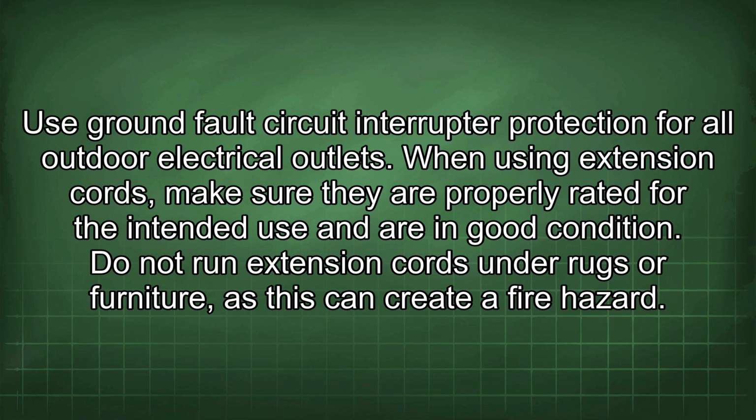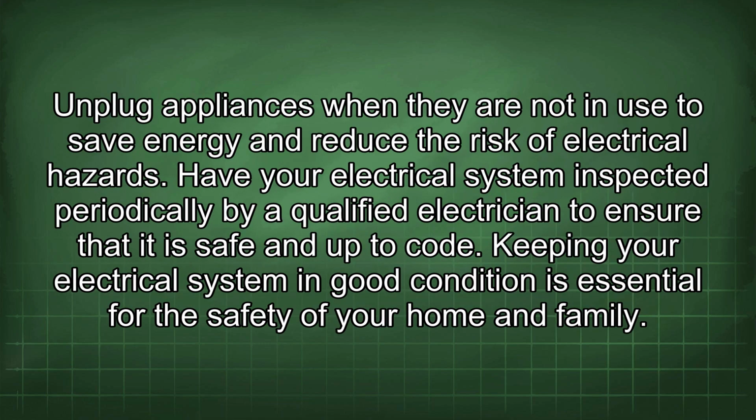When using extension cords, make sure they are properly rated for the intended use and are in good condition. Do not run extension cords under rugs or furniture, as this can create a fire hazard. Unplug appliances when they are not in use to save energy and reduce the risk of electrical hazards. Have your electrical system inspected periodically by a qualified electrician to ensure that it is safe and up to code.